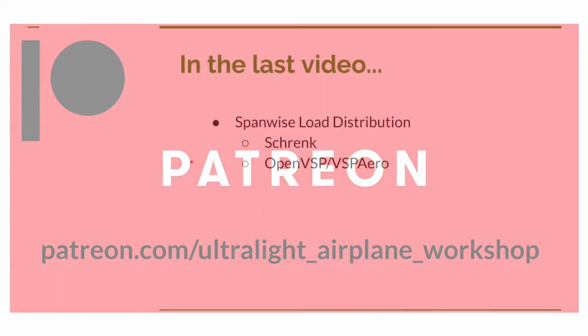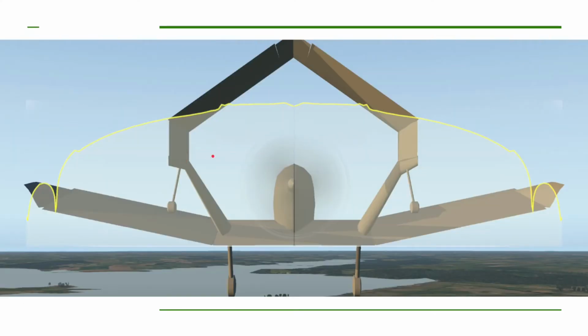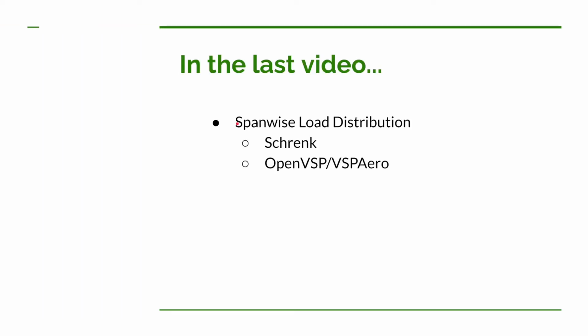Thanks a lot. Now, a quick review of what we talked about in the last video. Again, we were talking about spanwise load distribution, and let's go to this next picture. So we're talking about how the load on the airplane's wings is distributed across the span, and that's this yellow line here. So the higher this line is from right here, the more lift we're getting. In this case, a spanwise load distribution is going to be pounds per foot, so that per foot is span. In this video, we're going to talk more about how flaps and ailerons affect that span load distribution.